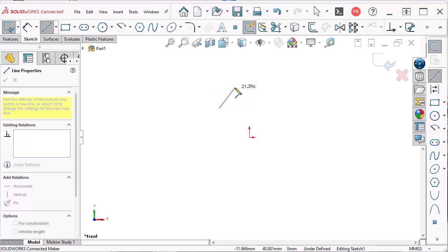If you see something like this, it's an angle symbol, obviously, but it's not yellow, so it's not going to be applied. You can also see dotted lines and a vertical symbol, but again, the vertical symbol this time is not yellow. The dotted lines are just inferencing that show that you're temporarily lined up to the origin. At this point, we're going to get a coincident relationship to the origin, and because the symbol is yellow, it will actually apply that relationship when I click.